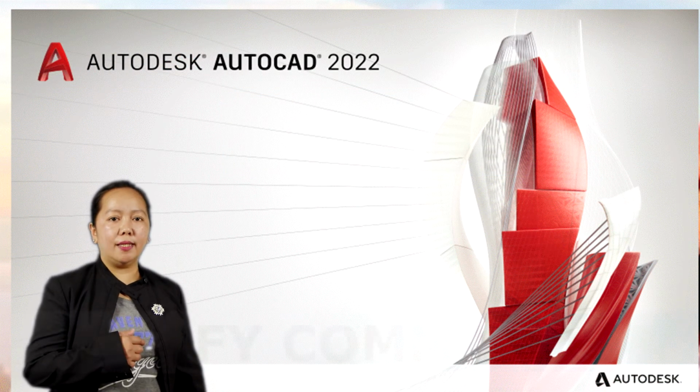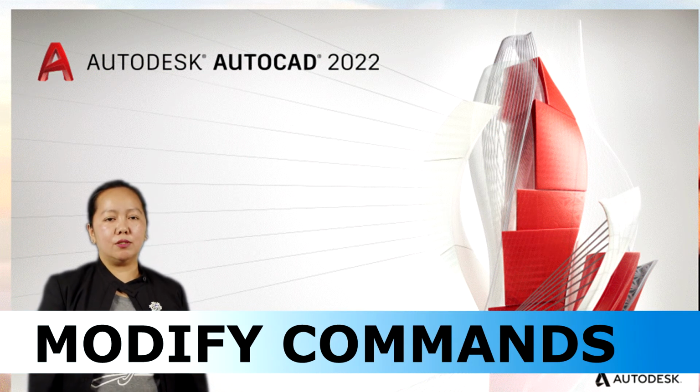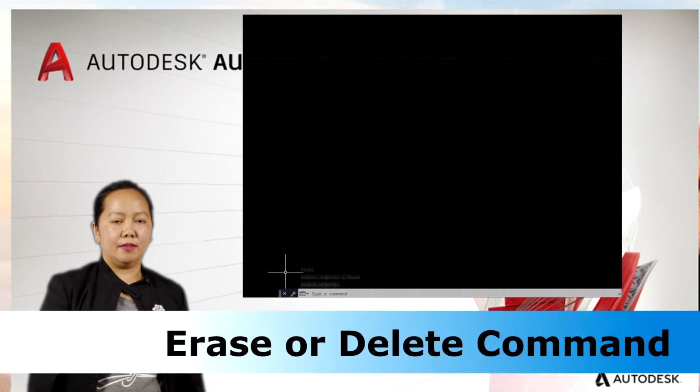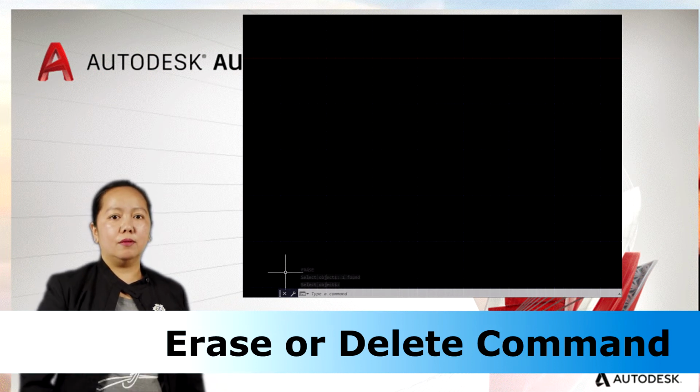Now, let's try the basic modify commands. The modify commands are used to edit objects in the drawing area. The basic editing commands are the following. Erase or delete command. The erase or E or delete command is used to remove one or more drawing entities.